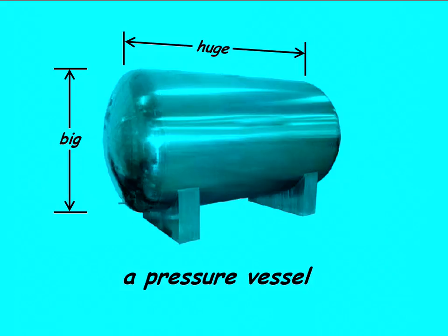So if the pressure was to rise in there, what would the hazard be? Bursting. It would burst. Yeah. You're not wrong with explosion, but first it would burst. So what would... If you don't have relief valves. Yeah, that's exactly it, yes. It's the one thing, I actually photoshopped the relief valve off this one on purpose. It's extremely rare to see a large pressure vessel like that without a pressure relief valve on it.